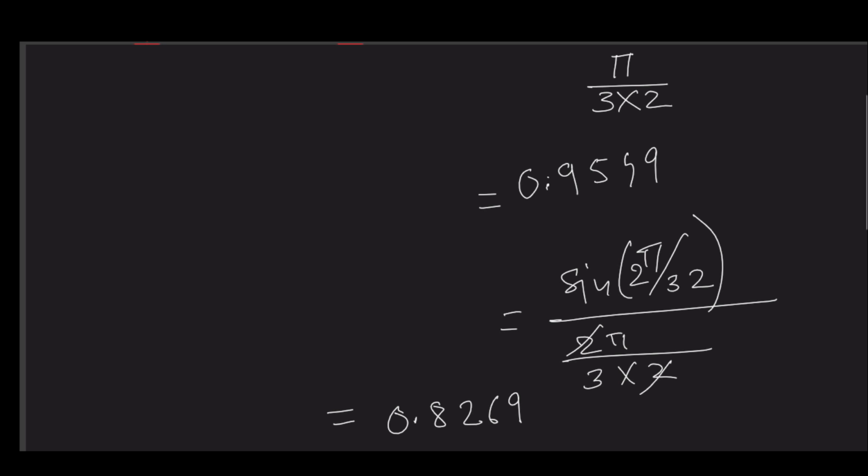So what is interesting to note here is that these widespread coils are giving a lower value of distribution factor, and that indicates that if we take higher order harmonics, then this widespread coil will give you more attenuation to the higher order harmonics, right?